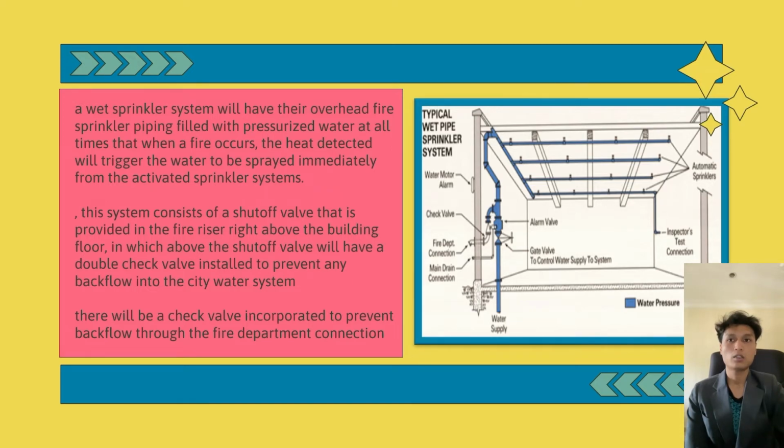The sprinkler lines contain fusible link sprinkler heads where the number, type, and location of it is determined by the fire occupancy rating. This particular rating will consider a few factors, and they include the type of structure, the material present in the area, the number of personnel, and the liability resulting from a fire.